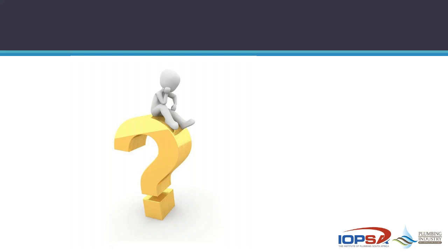And funny enough, one of the things that is mentioned in a study that I read a while ago is that if you go shallow and wide, the sun and the wind, especially in PE, actually helps to dry out that soakaway. So the expected life of that tank should be forever. It's the soakaway that might become a bit of an issue. And somewhere along the line, if there's a hassle, or the thing stops working or it fails, most of the time they end up digging a new soakaway, and Bob's your auntie, and that tank will just continue working.